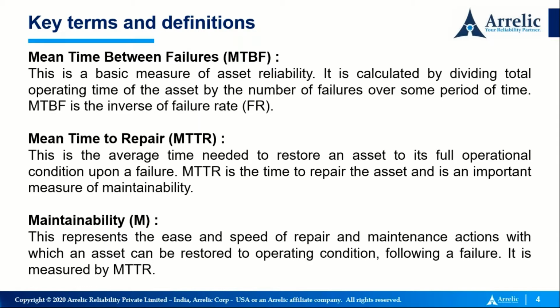Mean time to repair, meaning average time to repair. This is the average time needed to restore an asset to its full operational condition upon a failure. MTTR is the time to repair the asset and is an important measure of maintainability.